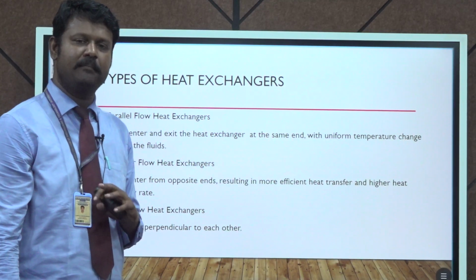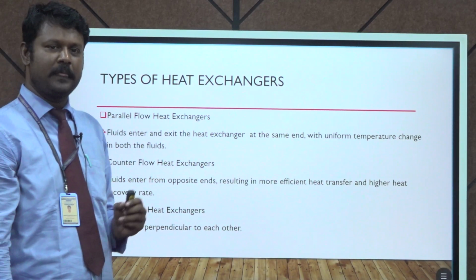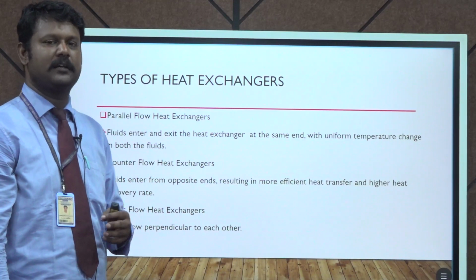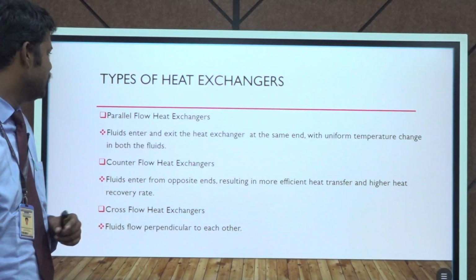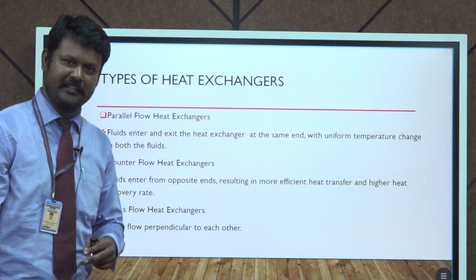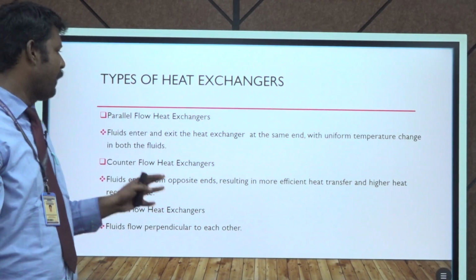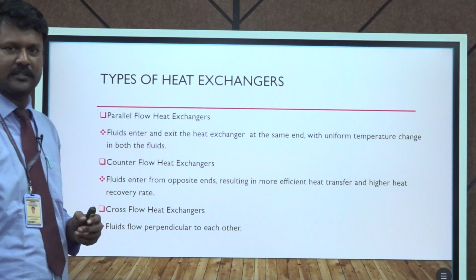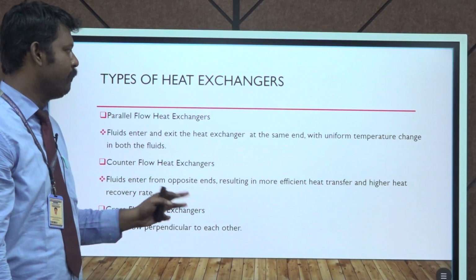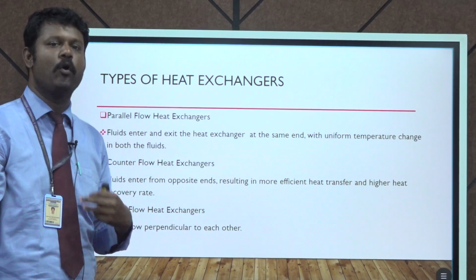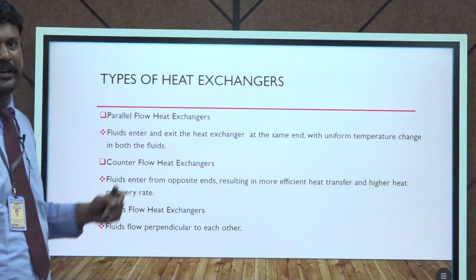Heat exchangers can be classified into many types. The types that are in our syllabus, and that we are going to see, are three: parallel flow heat exchanger, counter flow heat exchanger and cross flow heat exchanger. First of all, parallel flow heat exchanger. What is a parallel flow heat exchanger? When both the hot fluid and the cold fluid have the same input region and the same output region, it is known as a parallel flow heat exchanger.